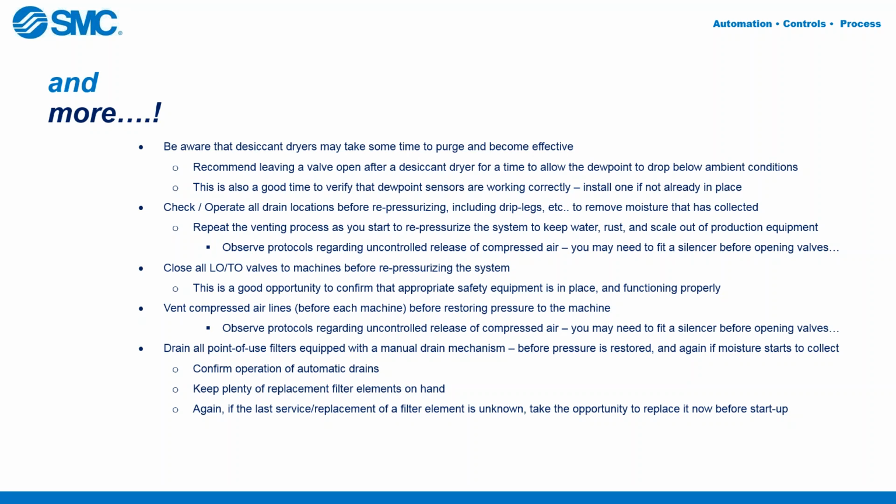This is also a good time to verify that your dew point sensors are working correctly. And I would recommend that if you don't have an independent dew point sensor, put one in. Take this opportunity to do that, because the gauge on a dryer is not always accurate.